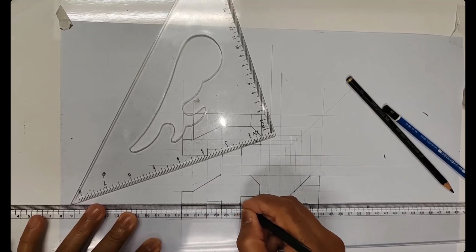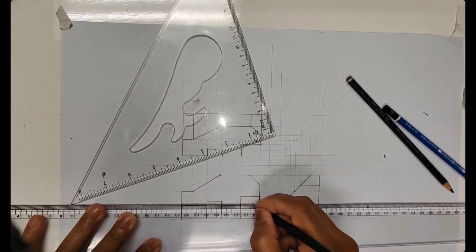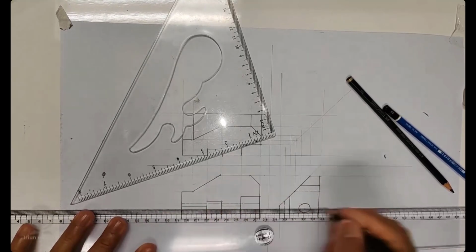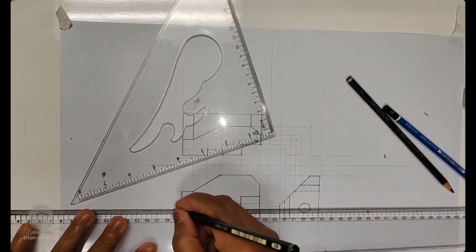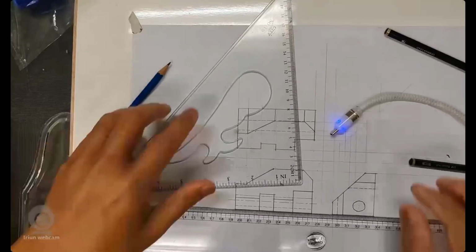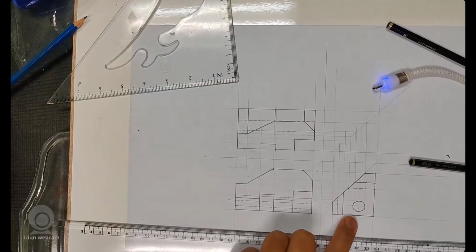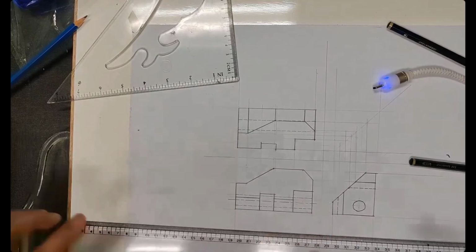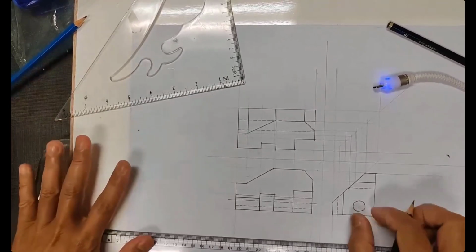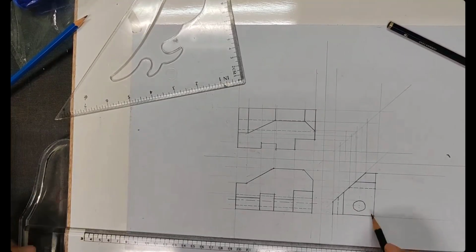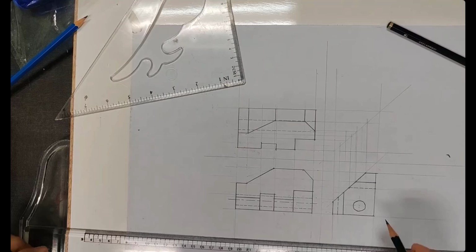I want to be quick but make it uniform. Okay, so the center line. You bring the extension line just now, then you make the center line. The center line must cut through. Before that, the construction of the through hole. Then I bring this hole there. The last thing to do is your drill through holes. Whatever it is, drill through hole, C-bore and so on, that's the last thing to do.